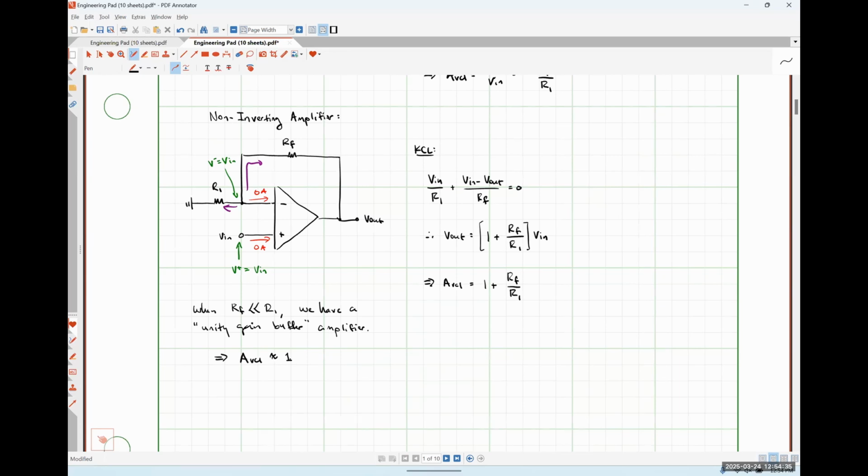However, the voltage that's generated by a piezoelectric crystal can be quite large. It's dependent on the rate of change of the deformation, but the current that's generated by such a sensor is actually really, really low. So if we wanted to use a piezoelectric crystal as a sensor, we would probably have the output of that sensor go through one of these unity gain buffers so that we get a really good snapshot of what the voltage is doing. And then we would use the unity gain buffer itself to supply current to subsequent stages as is necessary. So trying to just clue you guys in on where these guys are applied.